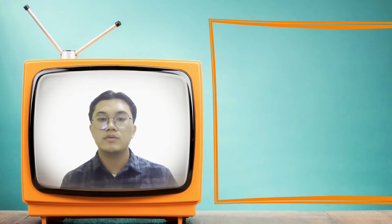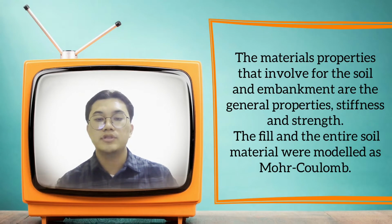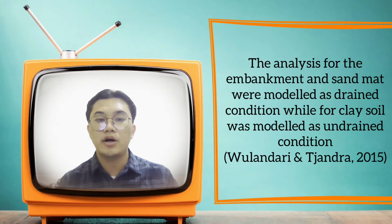The second one is the soil property. The material properties involved for the soil and embankment are general property, stiffness, and strength. The fill and the entire soil material were modeled as Mohr-Coulomb. The analysis for the embankment and sand mat were modeled as drained condition, while the clay soil was modeled as undrained condition. The soil property can be referred to the previous study made in 2015 by Wulandari and Tjandra.